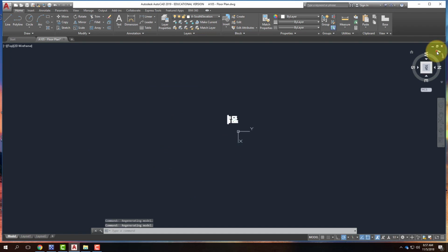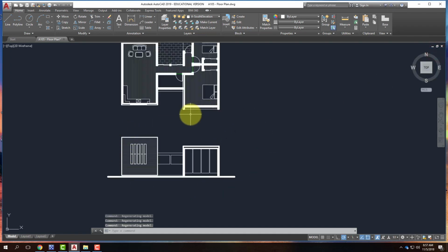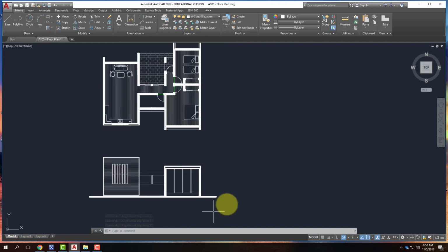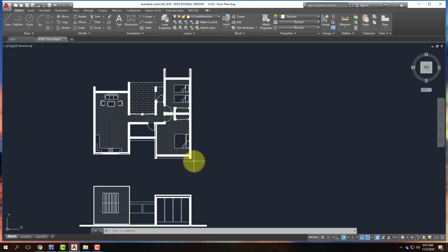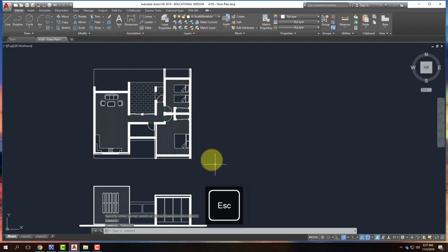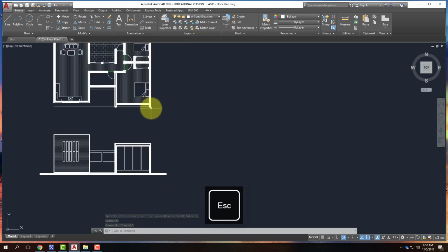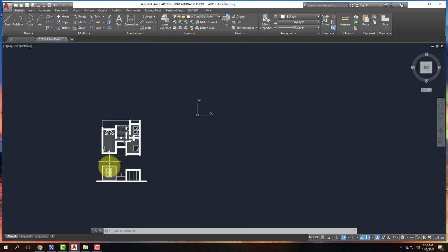Before I actually do that, though, I want to show you the relationship among all of these building elevations. So we went ahead and we drew this to start. But if I were to create a bounding box around my overall building elevation, and what I mean by a bounding box is completely contain my building inside of a rectangle. So I'd start at that corner. This would be the outermost point along here. This would be the outermost point along there. I would have a rectangle that looked like that. That would be my bounding box. If I were to have that bounding box, and I were then to have a 45-degree line extending from each corner, I could use the heights here to draw the elevation there.